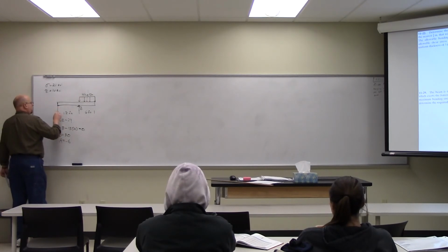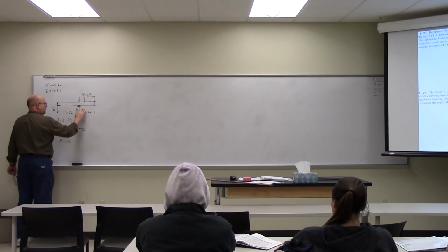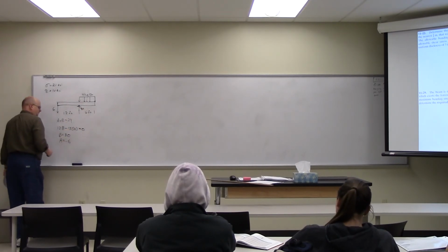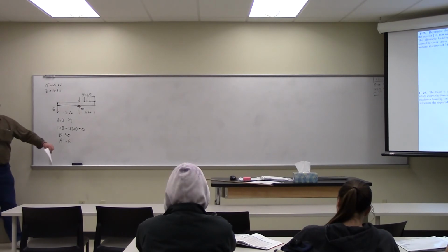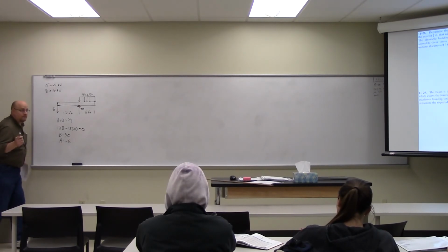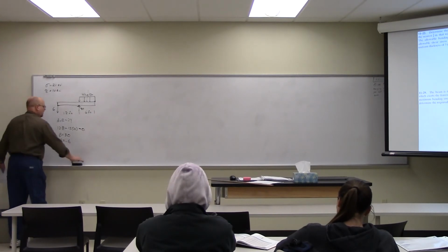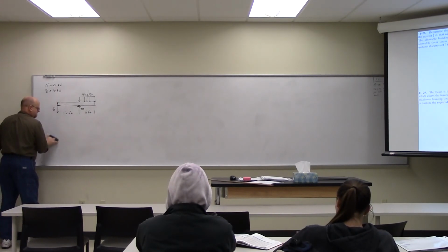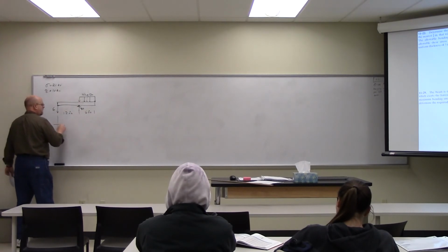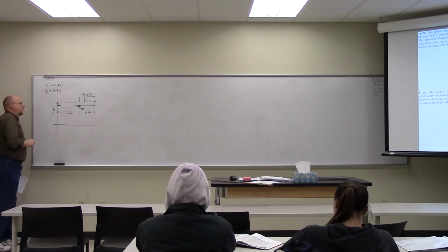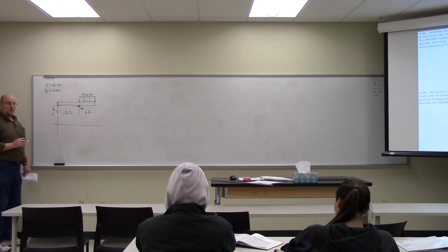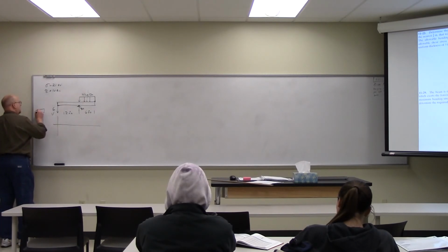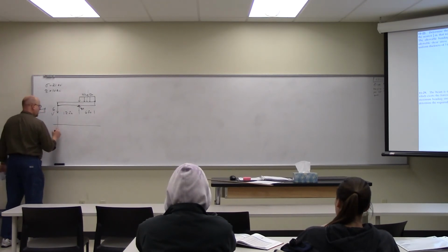Okay, so we have 6 kips pulling down here, and the force pushing up there of 30. All right, now what? Shear and moment diagram. What do I start out with? Shear on the left. What's that? -6, right? Because, again, this is down, so this has to be up, which is turning it counterclockwise. So -6.